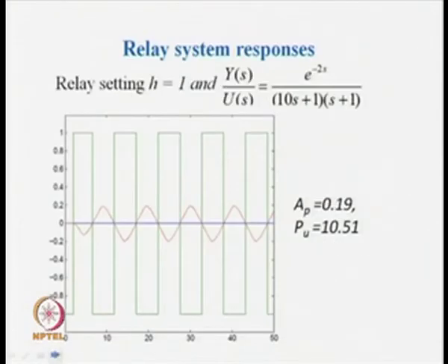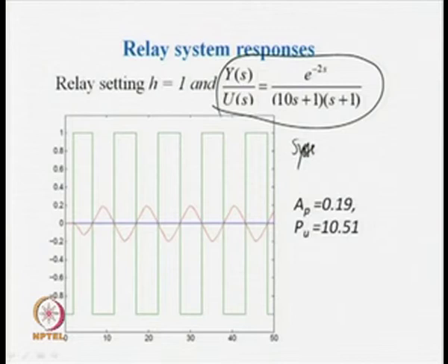Next we shall see what sort of output waveform is expected from higher order system dynamics. When a system is of higher order, it can always be represented in the higher order transfer function form of K e^(-θs) / ((T1 s + 1)(T2 s + 1)).